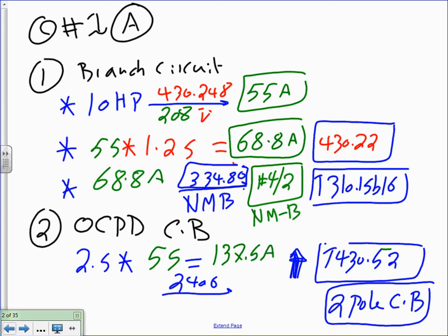Okay, then, because they don't make 137.5 amp circuit breakers, we'll take 137.5 to 240.6. Everybody knows 240.6? To us Minnesotans, it's like saying Vikings. You don't know Vikings, you don't live in Minnesota. So 240.6, when you graduate from here, you're going to say, I know exactly.